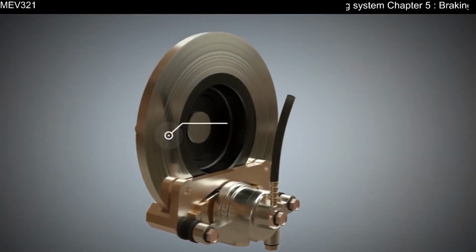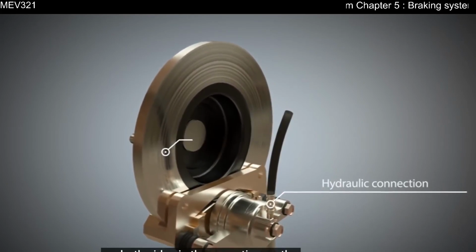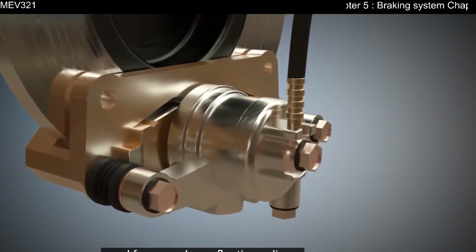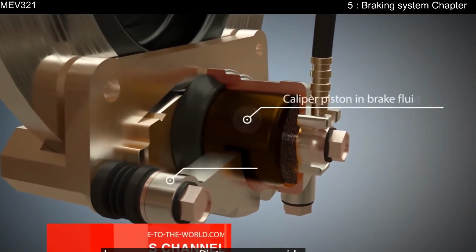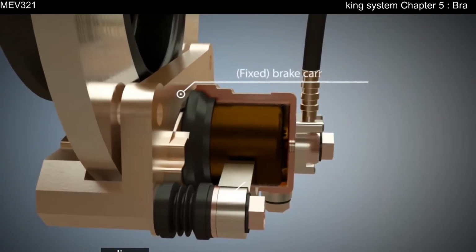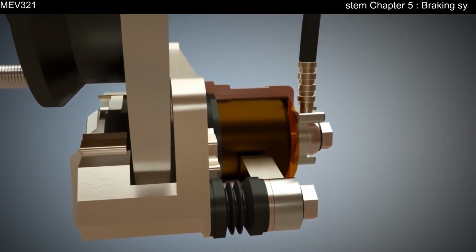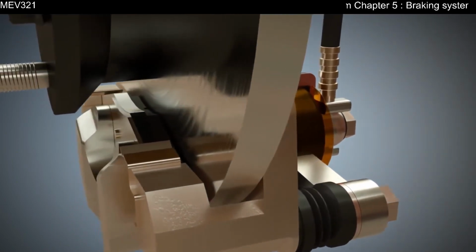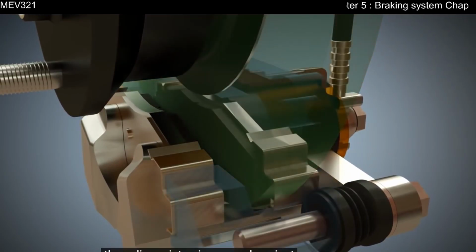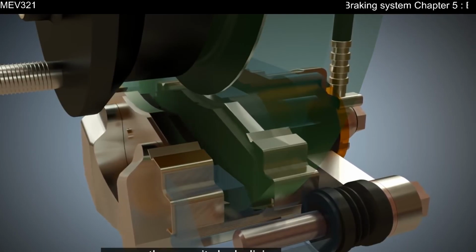A monoblock caliper with caliper pistons on both sides is the exception on the road. More often, floating calipers are used for normal cars. Floating calipers have one or more pistons on one side. Floating calipers are cheaper than fixed calipers. The caliper piston is pressed against the brake disc by pressure, whereby the entire caliper slides backwards and presses the opposite brake lining against the brake disc.